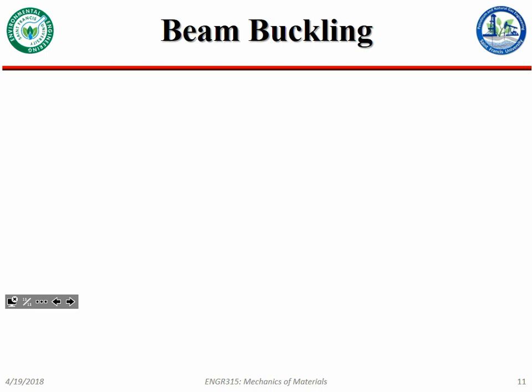And you might say, okay, whatever, that's just because the tube's kinked to begin with. But you can do the same thing with a whole lot of different things. Like here, if I press down hard enough, you see how this is starting to bend too. If I was making a column to stay straight and to support something, the fact that it's kicking out to the side and is about to collapse is a failure, right?